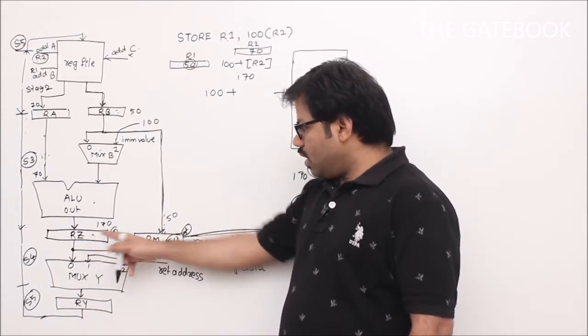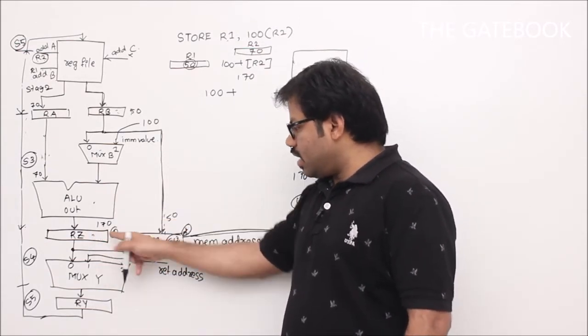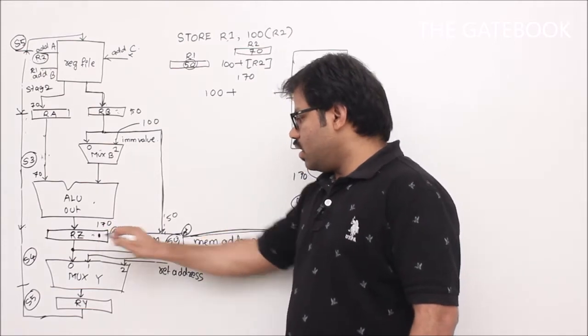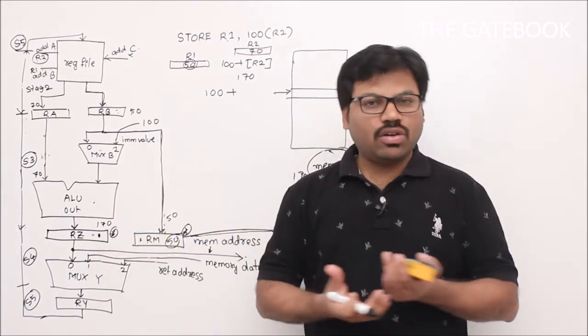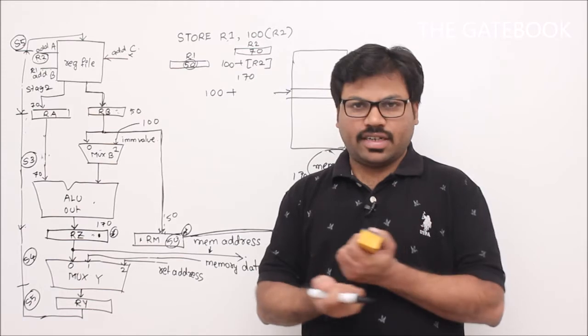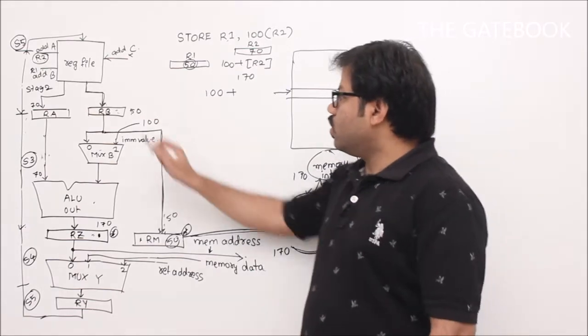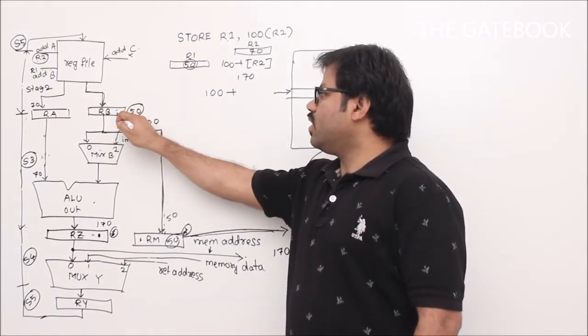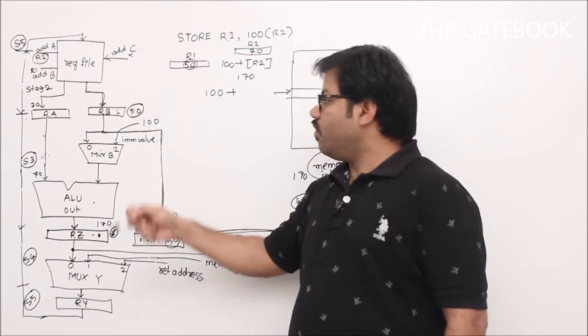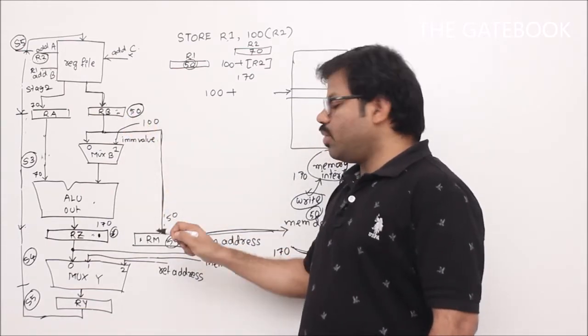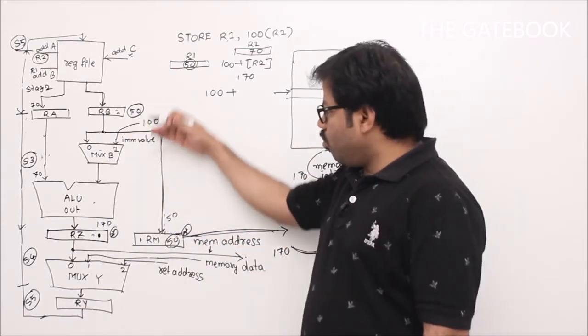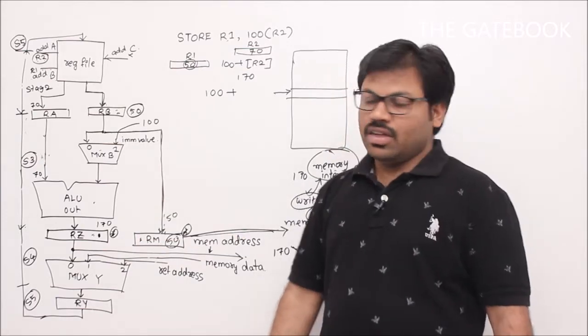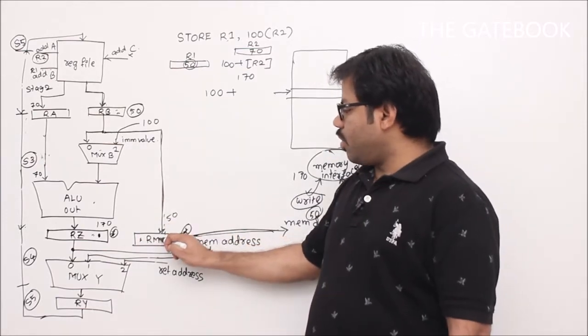There are buffers between stage number 3 and stage number 4. See, this is one buffer, this is one buffer. Those buffers are going to help us hold the data, correct? Though we have data 50 here, which is in stage number 2, we simply moved that to stage number 4, propagated it. So that's why this extra buffer is required.